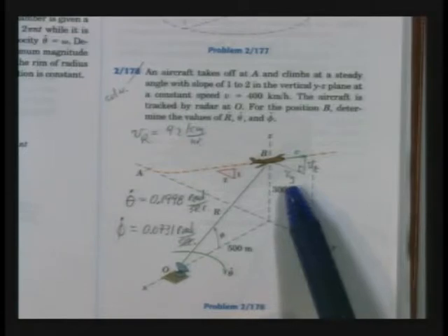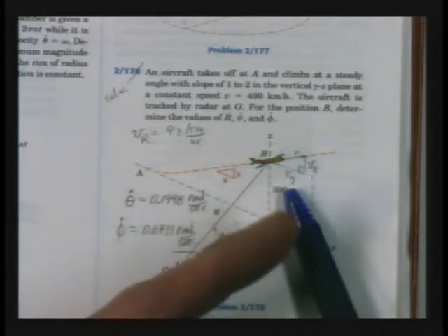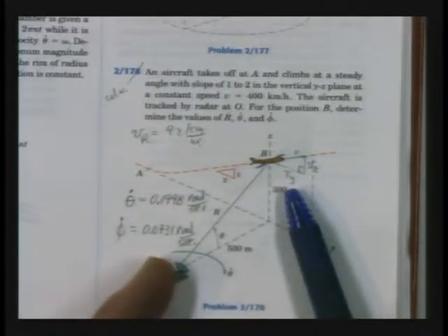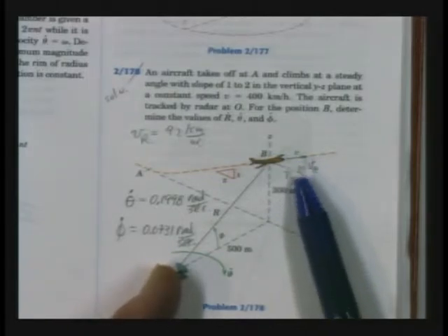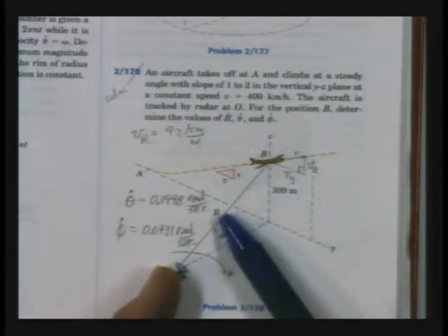It's going to play a part in the rotational part of this tracking device. So you don't use the entire V. You have to use that Vy component, because that's what's causing this capital R vector to rotate to your right.